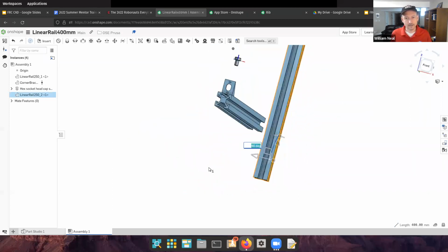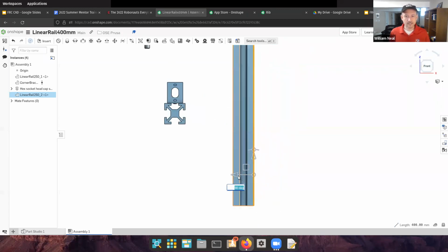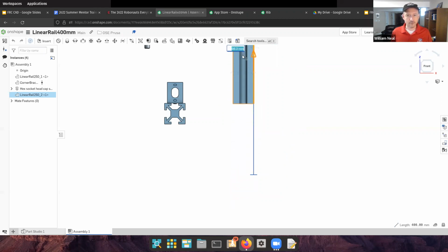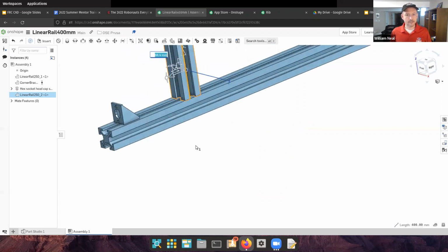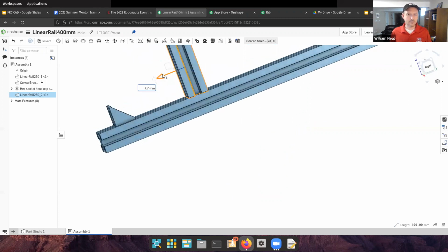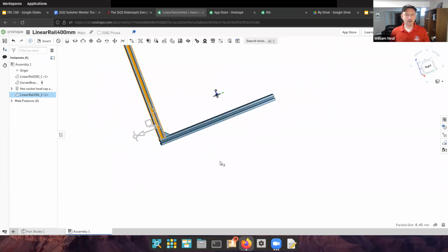Now I may take a look from the front view, pan it up, zoom it in, and we can see here I'm going to grab this handle and move it up till it's about at that point, and I can move it over here. So I've assembled it sort of how I want it, except now it needs to move over this way. Great. So that's the basic moving around. These handles appear by double clicking, and then I can change the angle or just move it in X, Y, Z direction and start making my parts come together.